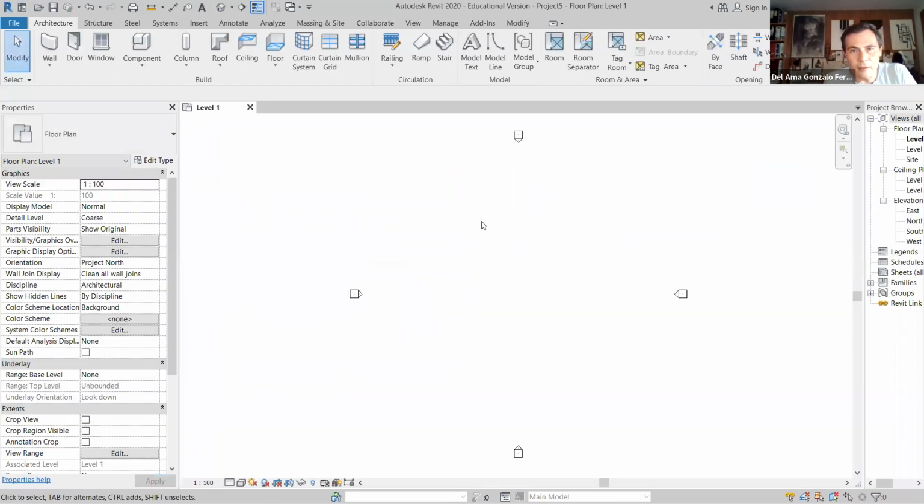Okay, so apparently nothing has changed. It's the same Revit interface. And here in the properties window, we have discipline. In disciplines, we have architectural, structural, mechanical, electrical, plumbing. So let's work with the mechanical discipline. We have to open a mechanical template, and we have to change this discipline to mechanical. Why? Because something might not work correctly if we are not working with the mechanical discipline.